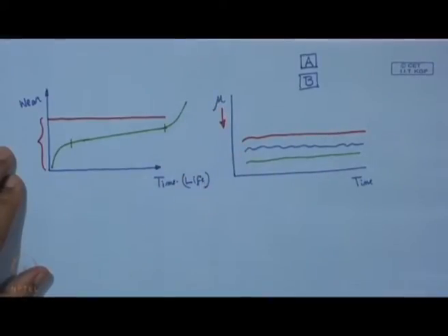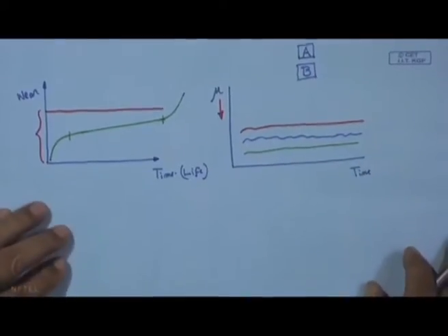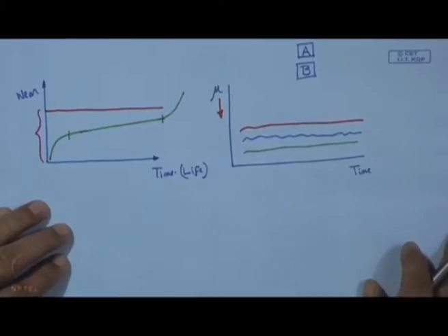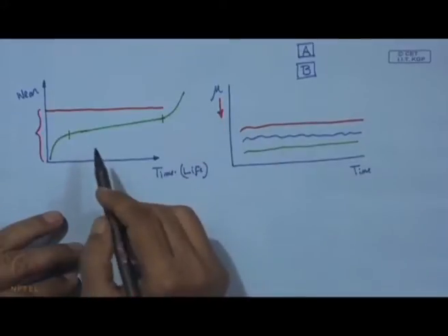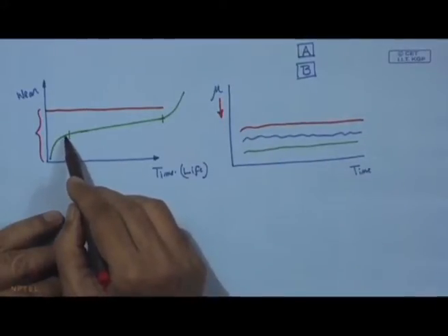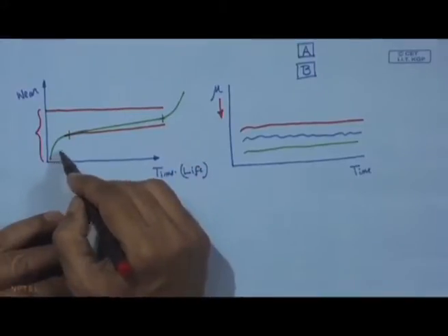Now, the thing is that when it is the question of friction and wear of surface coating, one has to look for a particular coating on a surface, say component A and B. Maybe on component A we have to have proper surface modification, either in the form of coating or just by changing the basic physical features of the surface of that particular component, so that with part A coated and in contact with B, the curve can also take a different shape, and our objective will always be to flatten this or to reduce this initial rate.